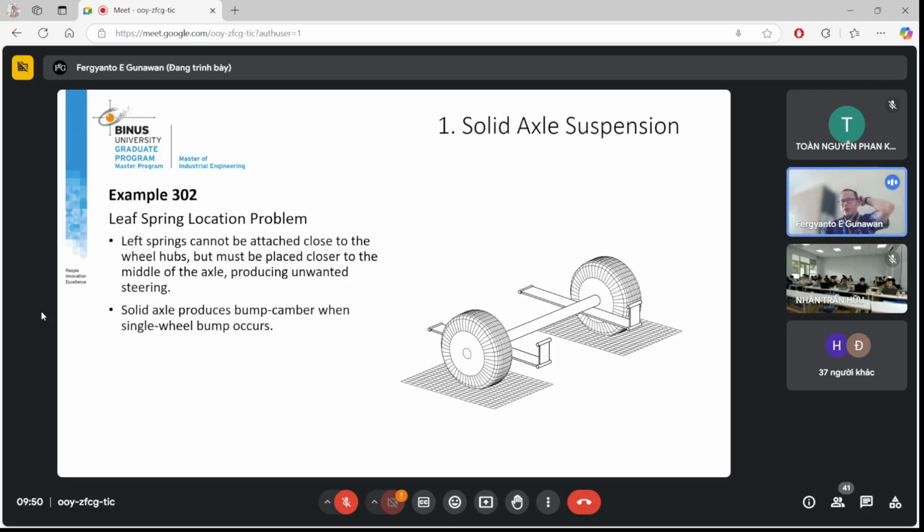You can't have a steering mechanism with leaf spring, right? So as a result, you can't attach a driving mechanism, right? So clearly this particular suspension is only applicable if you put it at the rear of the vehicle, not at the front of the vehicle, where steering mechanisms are necessary. That is sort of the limitation.